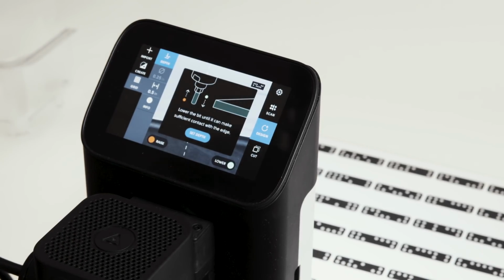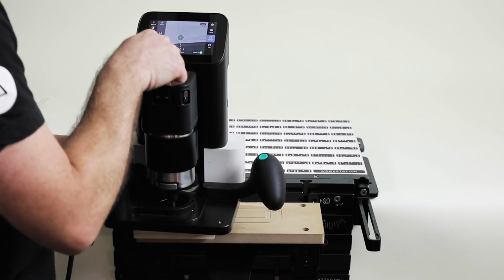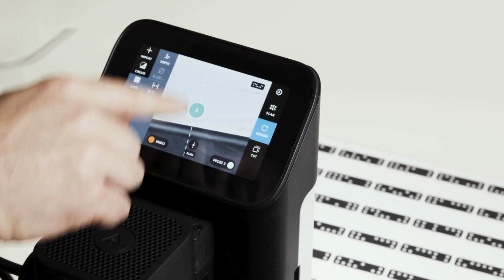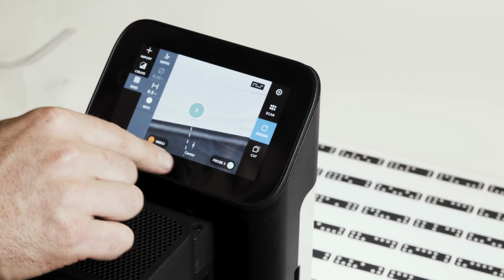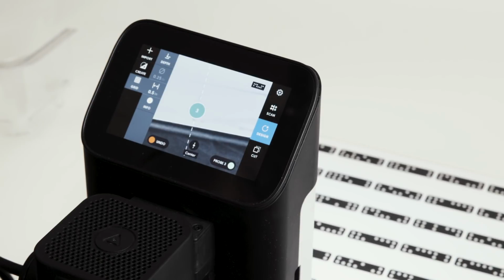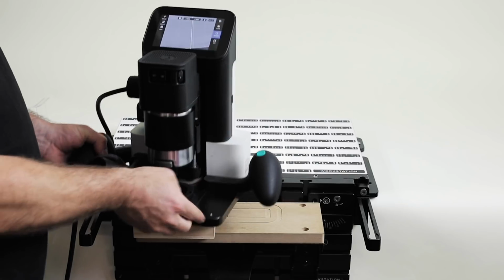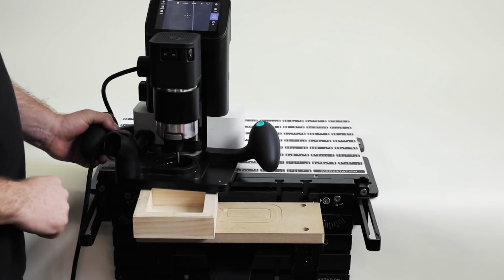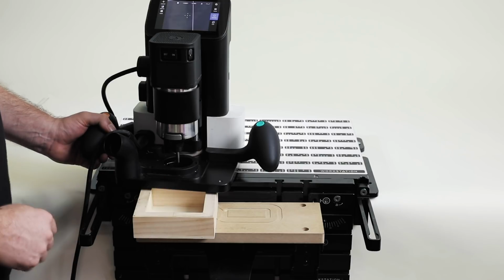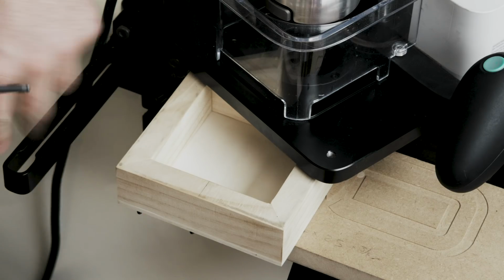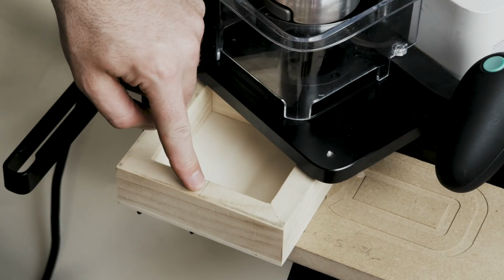Perfect. So I can now see down here that I'm perfectly aligned, set depth, and auto, because I'm between those 2 points, automatically it's going to use a center probing option. I can override that, but I do want the center option. So I'm going to hit the probe button. Now I have a position where I can confidently place geometry relative to that edge and that pencil mark. So for things like door mortises, hinges, that sort of thing, that comes in really powerful to quickly know that you're 100% parallel to that edge and centered on that line.